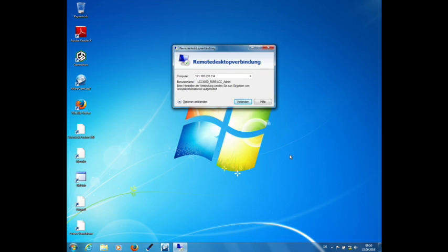If the vacuum degrades over time, well, first of all, vacuum gauges have no absolute vacuum reading, so you need to have some sort of reference. You should always think of your vacuum reading in the main chamber as a relative reading.